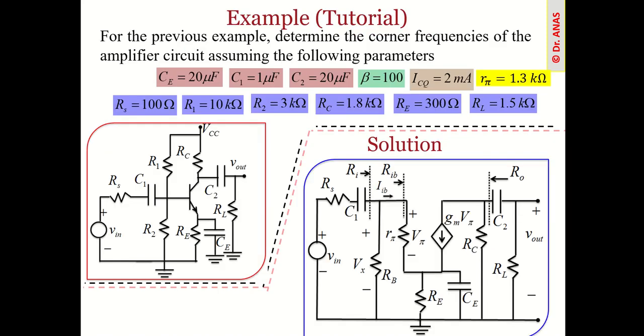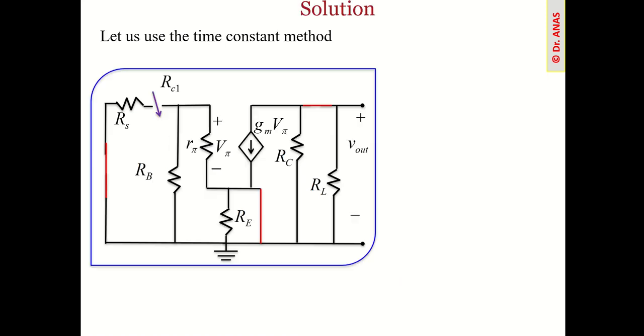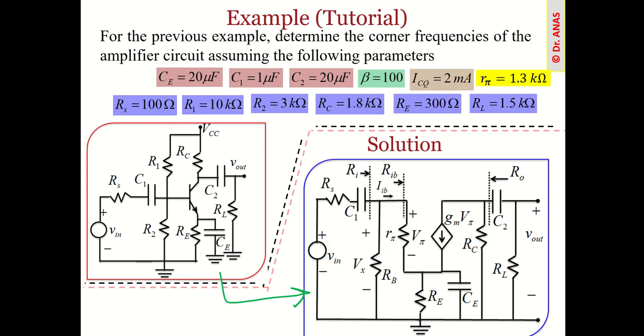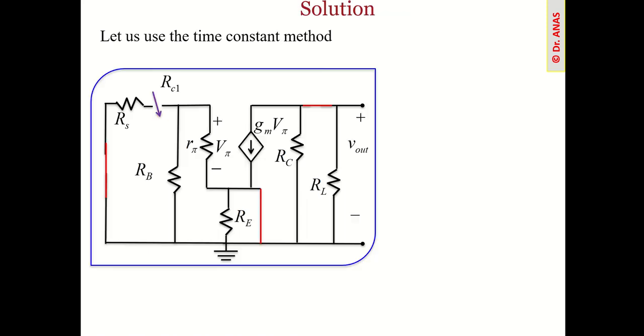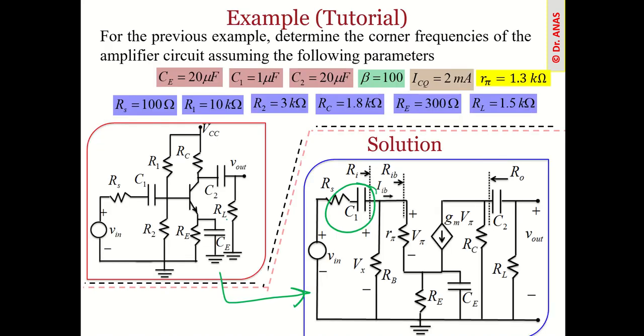This is another example. Okay, like we have more capacitors here, so that will be the AC model for this one. And now again quickly, for example, let's try to find the resistance seen by this capacitor. So for this case, our circuit will look like this one. Okay, so voltage source is short circuited. Now here see, we have a capacitor.